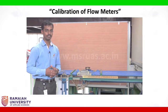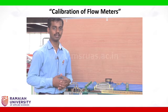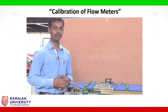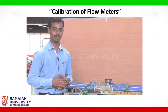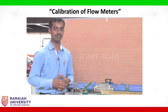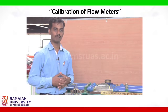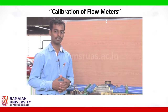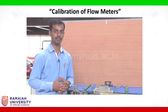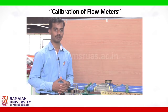After taking all the readings, there shall be some errors between the rotameter values and the orifice meter values. Remember, we need to take the calibrated rotameter values and not the actual rotameter values, because the calibrated rotameter is acting as the standard for calibration of the orifice meter. Now, after taking all the readings, we can measure the errors between all the different readings and then calculate the correction factor that has to be adopted for the orifice meter in order to calibrate it.